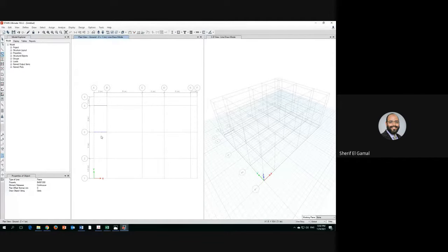Let's add another beam, a third beam, a fourth beam. So I added 4 beams at the ground floor level. These beams are all 400 by 200. Then let's add some other beams here. This is 8 meters, so we'll take the biggest one. Here we'll take the 600, maybe you can make 800 by 200. Yes, no problem. So I'm going to click here.